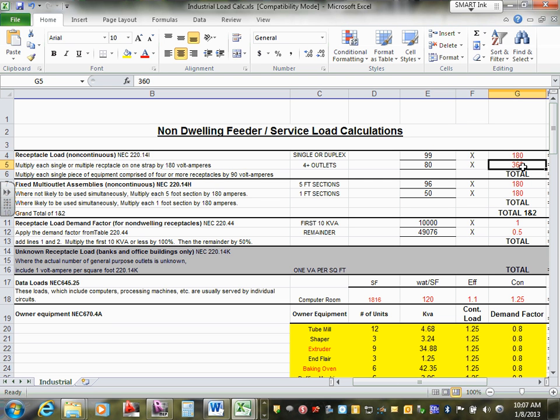The only thing I would like you to change, guys, here, they're multiplying. Remember that was 90. Change this one to 360, will you? So this will be 90 of them multiplied by 360. Because these are quads. Each single receptacle in the quad count is 90. 90 times 4 will give you 360. So that number has to be multiplied by 360. We just have the times 4. Not a biggie. Account for it, though. Everybody's there?